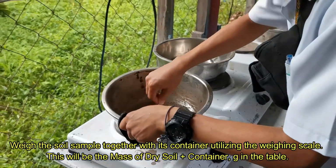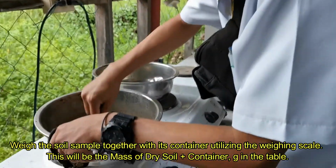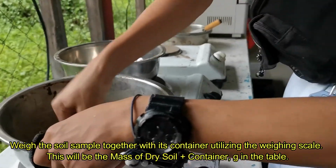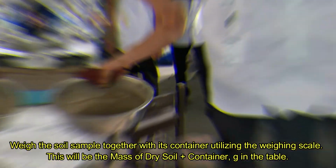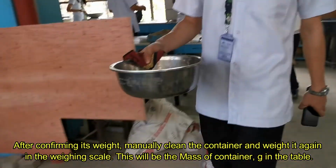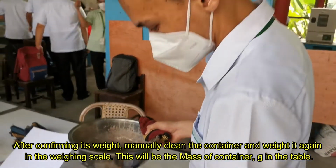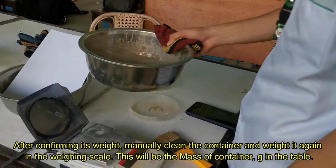Weigh the soil sample together with its container utilizing the weighing scale. This will be the mass of dry soil plus container, in grams, in the table. After confirming its weight, manually clean the container and weigh it again on the weighing scale. This will be the mass of the container in grams in the table.